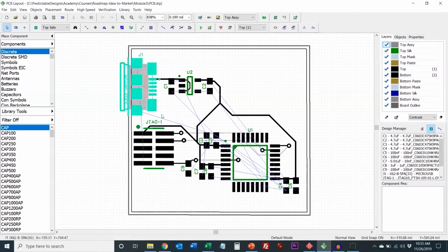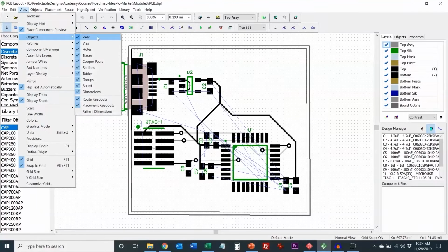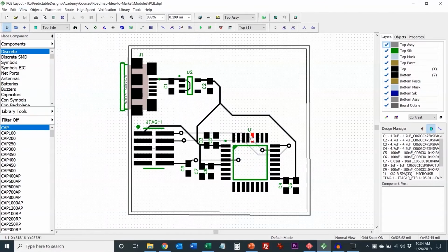These are just sort of for visual guidelines when you're doing all the connections. You can see how the things are connected before you draw on it, the signal traces. These blue lines are not really there. I'm going to go ahead and turn off rat lines just because they make it a little ugly of a design. This is the USB connector.